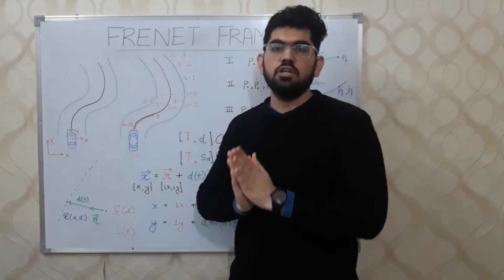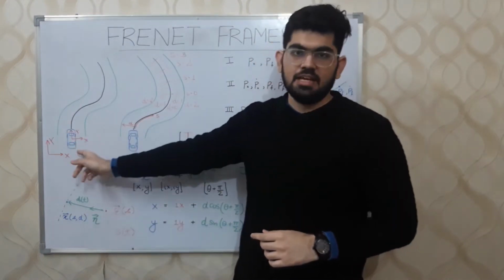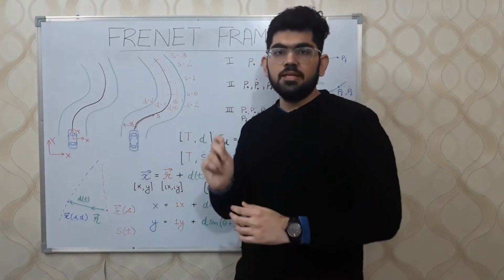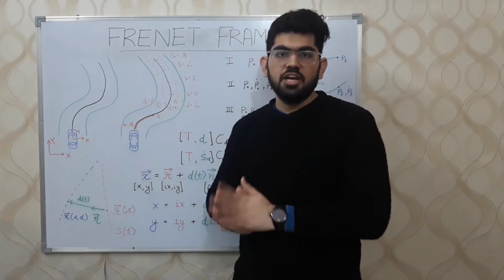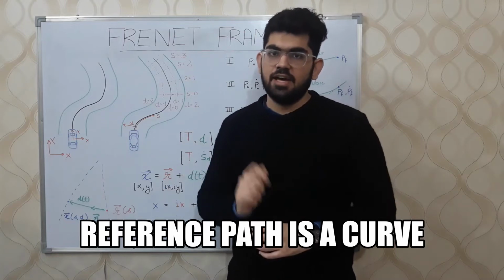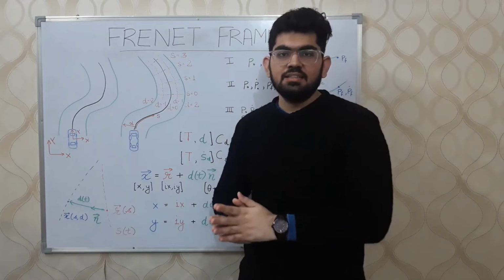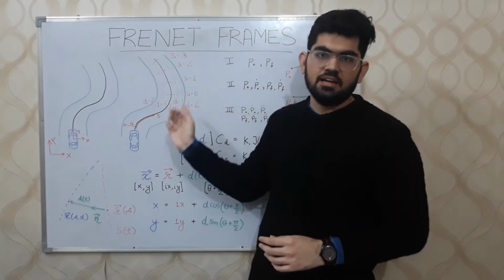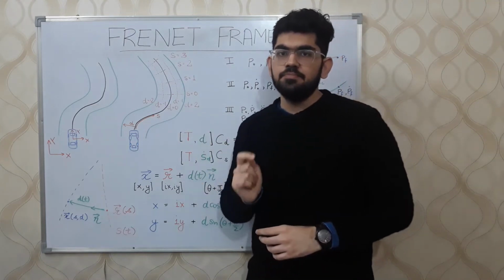and we are also going to have a coordinate frame that is fixed on our self-driving car. Every point on this global path will be represented with respect to this coordinate frame. We are going to have a curve dependent on the values of x and y. In the Frenet frame, we have the coordinate axis that is defined with respect to this curve that we already have. We represent the two coordinates using s and d.